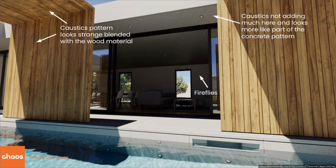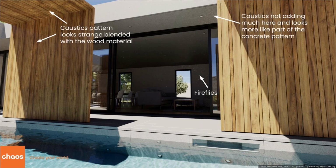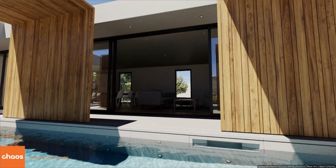So in this case, we're going to take all these elements that we just talked about, and we're going to exclude them from receiving caustics. And this is then the end result. Now, the idea here is that you can use this as sort of an art directable thing. So if you don't like patterns in the upper left corner, you can just exclude that object from receiving caustics, right? The pool's still going to have caustics. That's really important, probably for this image. But those other parts are not going to have them.